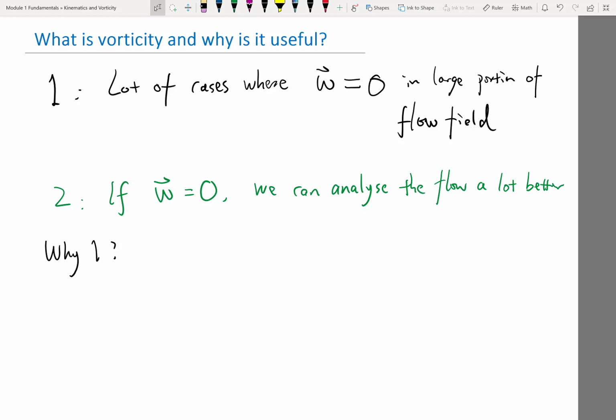Okay, so let's start with the momentum equation. The momentum equation, as we have always been saying, is rho partial t, plus the divergence of rho u, so this is a tensor product, plus a gradient of p is equal to viscous forces. Let's defer viscous forces to later, because we'll see that if there is viscous force, there is a mechanism of generating vorticity.